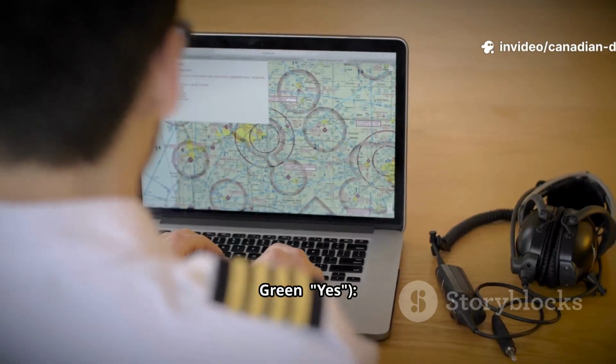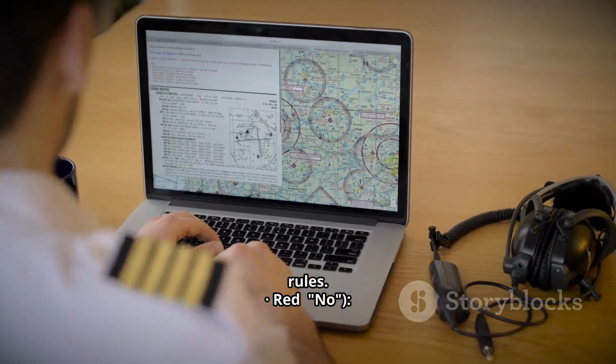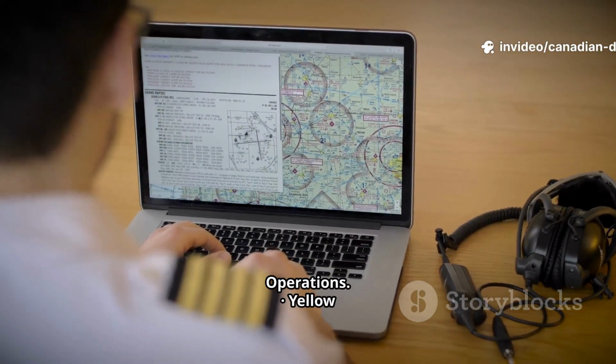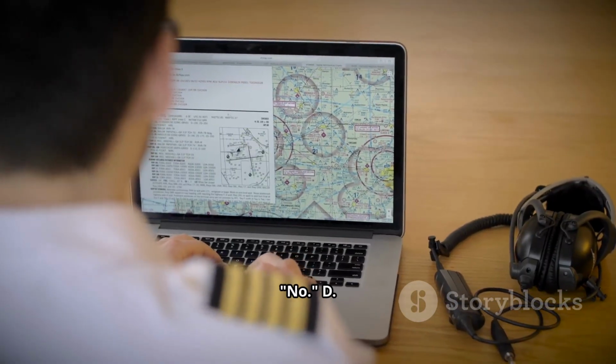Green. Yes. Uncontrolled airspace, Class G. You may fly here following the basic rules. Red. No. Controlled airspace, Class C, D, E, etc. You cannot fly here under basic operations. Yellow. Maybe. You need to review the specific restrictions, for example, near a heliport. For basic ops, treat this as a no.